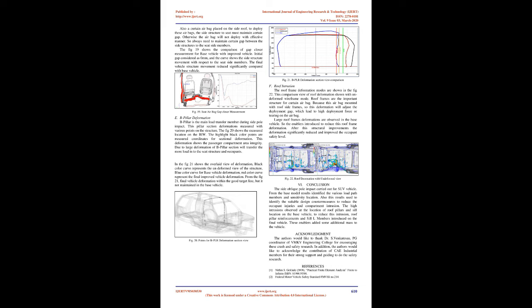D. Seat deformation. The first row seat structure is shown in Fig 18. Seat structure is one of the major systems for occupant safety, since the occupant is belted with the seat structure. The strain contours show the base vehicle seat structure experiencing large deformation. This happened due to large load transferred from the side structure. This has been eliminated because the side structure stiffness is improved.